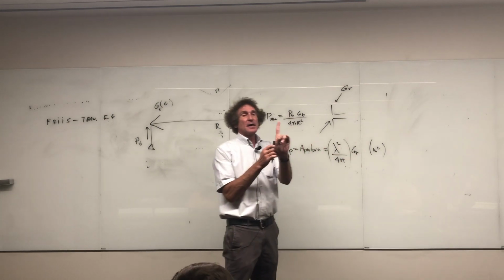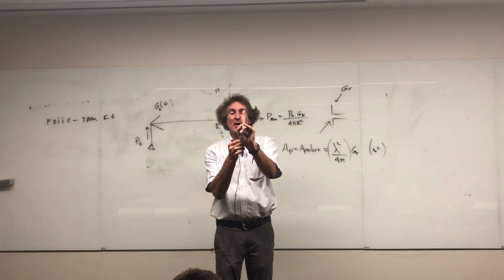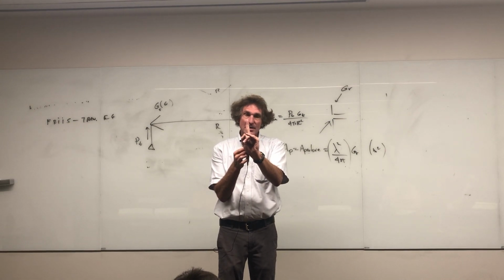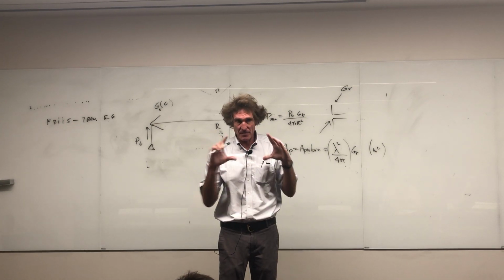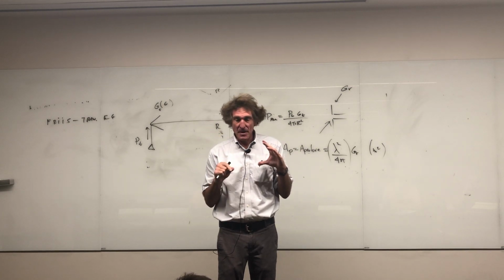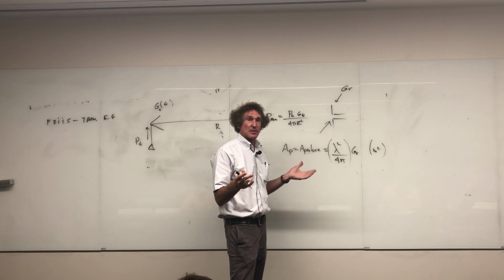But still, people get caught up in this. They say, well, when it's a thin wire and this long, it's just the diameter times the height. And that's not what the electrical area really is. At very high frequencies, it turns out to be the physical area of the antenna, when you have many, many wavelengths that cross the diagonal. But for these, the electrical area is found by doing this. That's how big it looks.